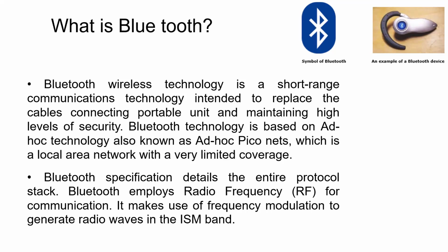This Bluetooth technology is based on what is called ad hoc networking technology. Ad hoc networking means this network is not like your infrastructure network, but it is on the fly or on the go type of network, in which there is no fixed infrastructure, and there is no master like a base station, though a master is still there.